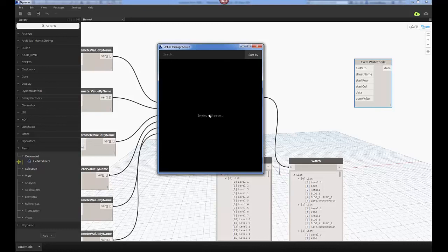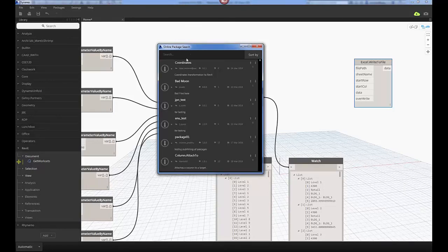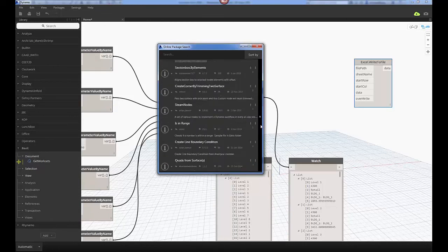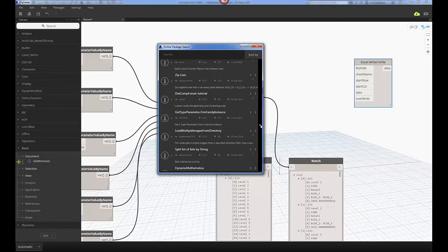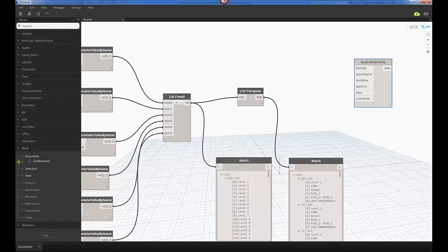Clockwork is a good one, with a lot of great tools that you use on a regular basis. Lunchbox is another one. You can pretty much just do a search, and depending on what you're doing, in a lot of cases find a node that will do it. You can also create your own nodes, and if you know Python, you can create your own Python nodes. So there's a lot of flexibility in here, and a lot of people are basically just creating tools that you can add.